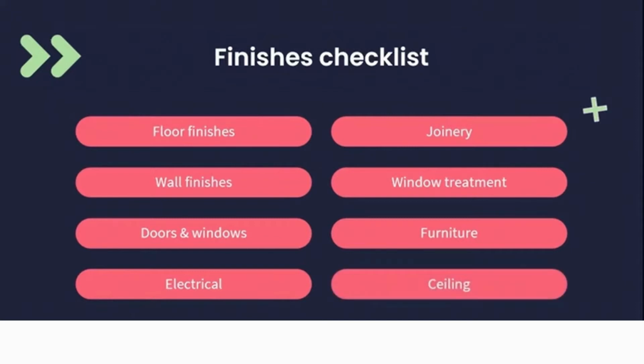And then lastly, I finish off my specification schedule, my finishing schedule checklist, looking at the ceiling finishes. So this could be anything to do with electrics that have been applied to the ceiling, as well as the actual finish of that ceiling. Some of the materials that you want to consider are plasterboard, coves, moldings, steel, lattice. Has the ceiling been plastered? Does it have a board applied to it? Has there been linings indicated in the ceiling? Have we used ceiling tiles, timber cladding, etc.?